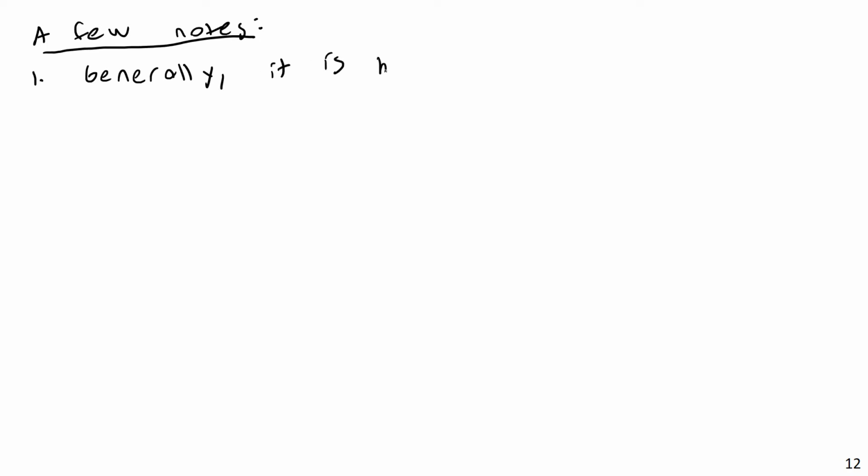A few notes. Let's take a look at a few notes here. One, generally it's beneficial to simply assume that all the members are in tension. This is what I usually do when I'm applying the method of joints: simply assume that all members present are in tension.